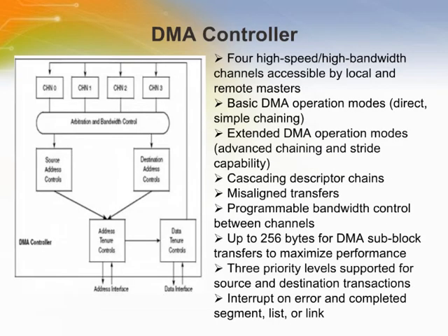The DMA controller has 4 high-speed DMA channels. Both the e500 core and external devices can initiate DMA transfers. All channels are capable of complex data movement and advanced transaction chaining. Operations such as descriptor fetches and block transfers are initiated by each channel. A channel is selected by the arbitration logic, and information is passed to the source and destination control blocks for processing. The source and destination blocks generate read and write requests to the address chaining engine, which manages the DMA master port address interface.